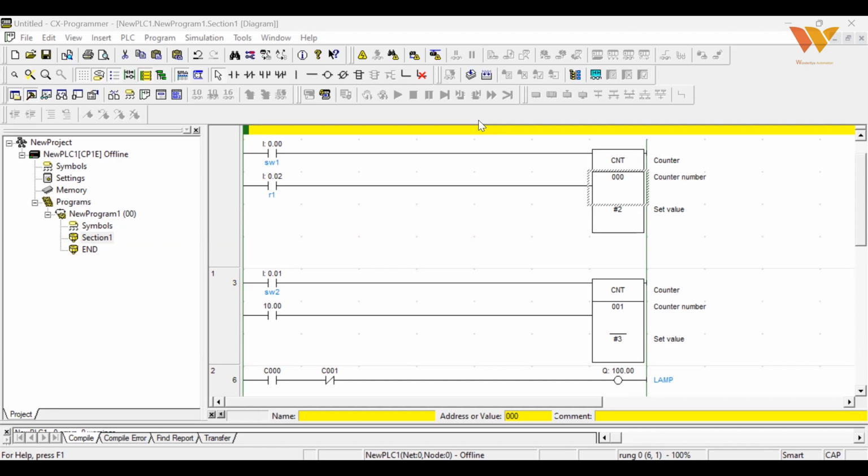So imagine Y2 and Y3 as lamps. When the tank runs for 5 seconds, liquid will fill up to the Y2 level. So Y2 will be on. Once Y2 gets on, you're making Y1 on for 10 seconds, okay? Yes. So that is the second run.